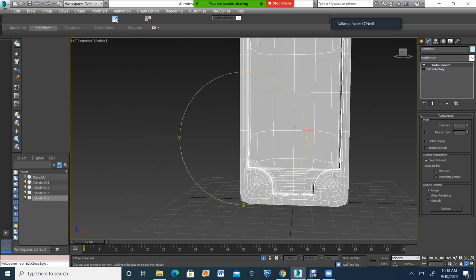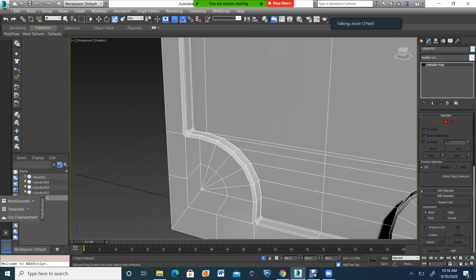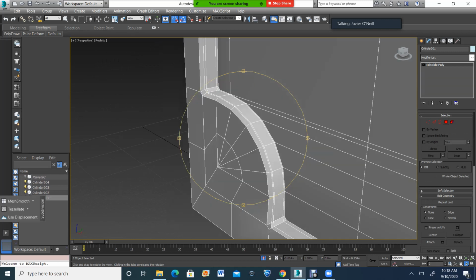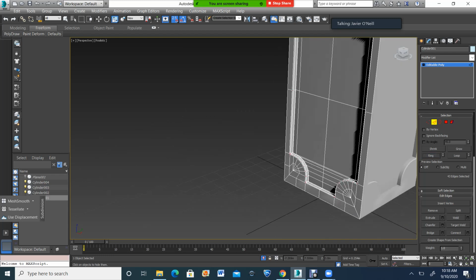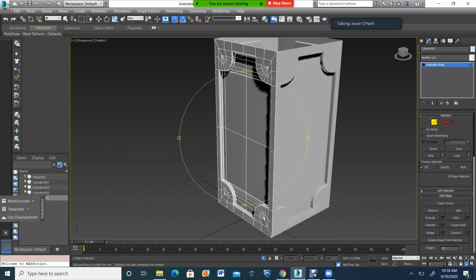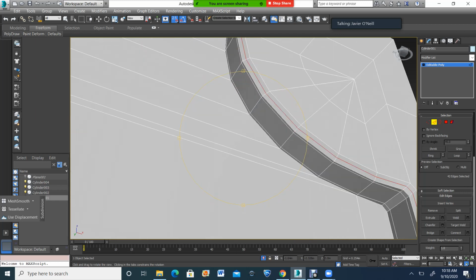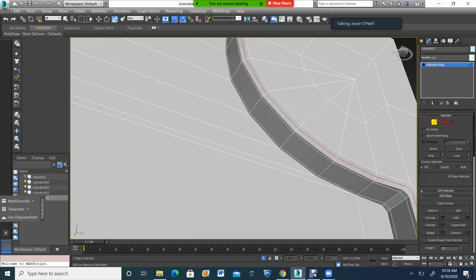So I'm going to hit undo on that, take that off, save it, and let's see, where else could I use another cut? This one, I think this little space right here could use another cut too, so I'm going to do ring, and since it's quadded, as you can see, it's all around, good. Control Shift E, and then I'm going to chamfer it again. Whoops, sorry. Chamfer.